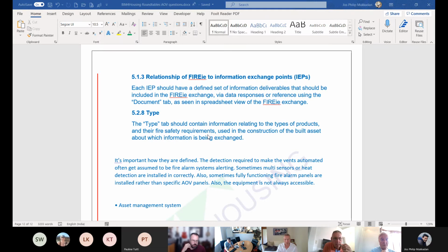I suspect that comes about because when the main contractor gives out works packages, they don't convey all the information to the specialist contractors. So if Will's team doesn't get told, oh, by the way, this system needs to open the doors and ground the lifts, they're going to put in an ISO-based system rather than a BS5839. And it's all too late by the time it's been installed.